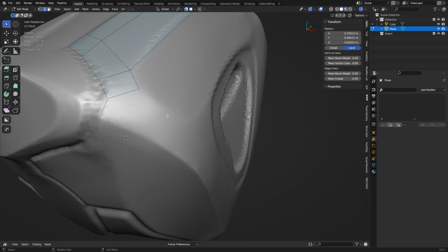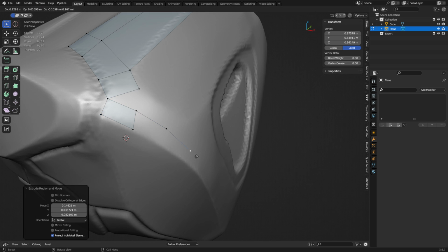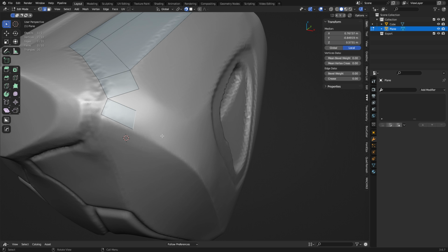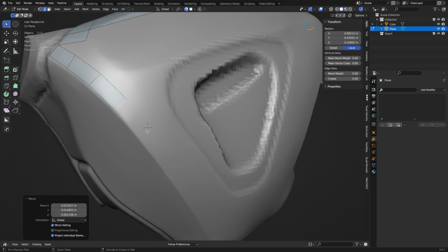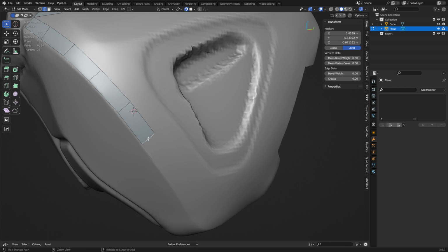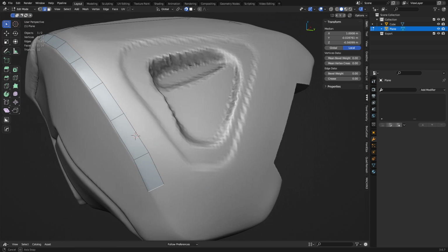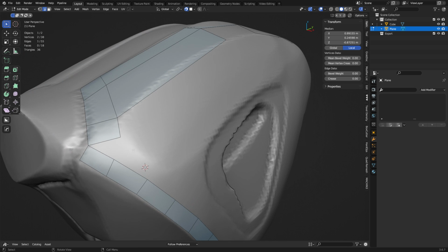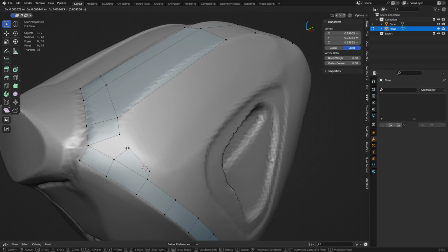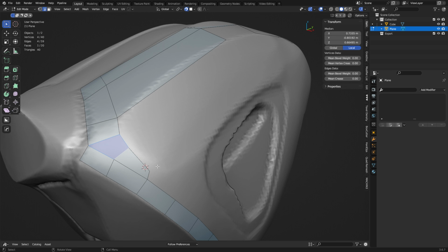Right? So we can take these two edges, press F, and we can keep running with this idea, or we can do the whole edge. We can hit E and extrude it out. But we can also hit Control and right-click. That's a cheater way of doing it. So don't be afraid of cheating when you're working on your projects. Saves you time, saves you effort. That's what the add-ons are all about. It's so that you can get things done quicker and faster. You guys that don't want to use add-ons, I understand, because that's how I learned Blender. I was not using any add-ons, but at a certain point, you're going to want to start exploring those add-ons for sure.